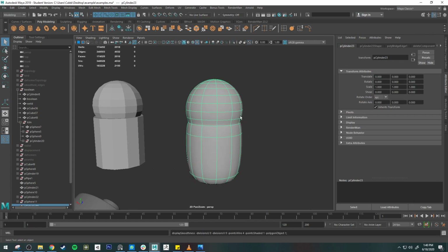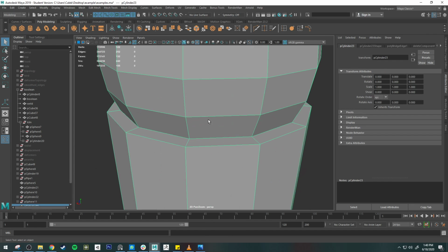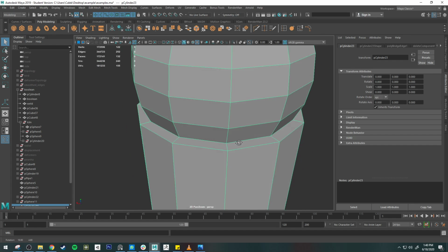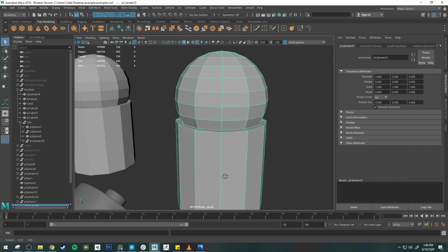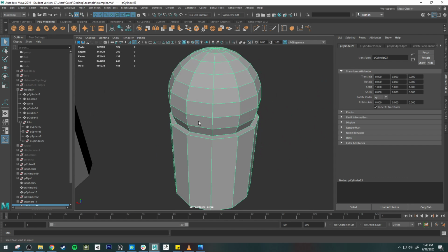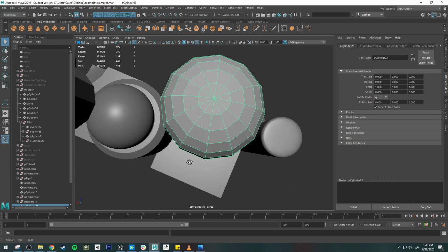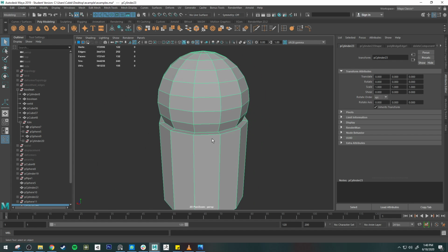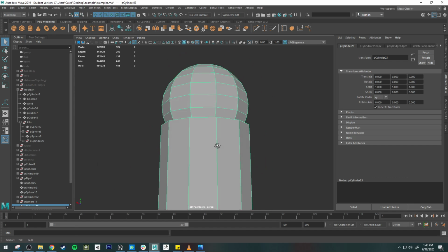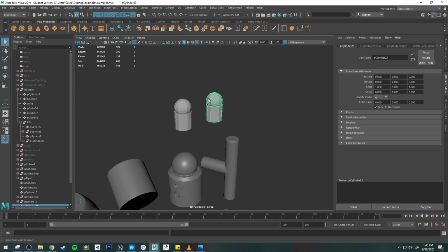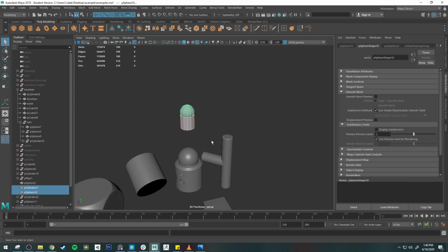The advantage of this would be, the earlier demonstration of this, it almost perfectly did it, but most of the time, about 90% of the time, 95% of the time, Booleans are not going to weld the points correctly, right? And so the nice thing about this is I won't have to really do any cleanup because I know the process of how I'm making this, and I'm doing it by hand, right? Whereas Boolean's going to do it automatically for you, but most of the time it's going to make some terrible geometry for you, right? Okay, let's take a look at a few of these other objects.